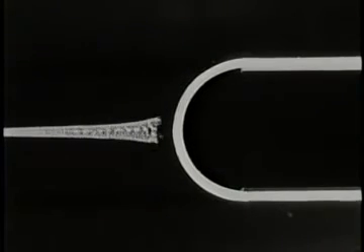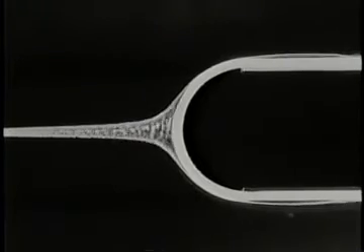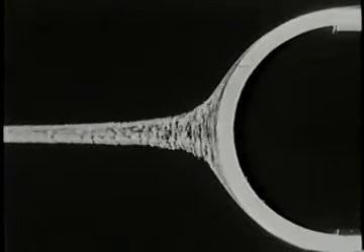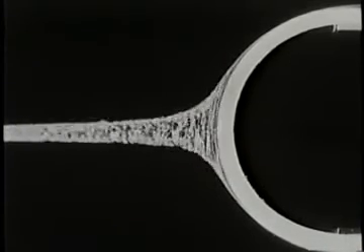Here is a streaming flow past a blunt body with a central stream tube marked by hydrogen bubbles. The widening of this stream tube tells us that the flow is decelerating. The singular point where the central streamline reaches the nose is a stagnation point. The speed is zero there. On both sides of the unique stagnation streamline, the fluid decelerates, but not to zero speed, and then slides around the sides.